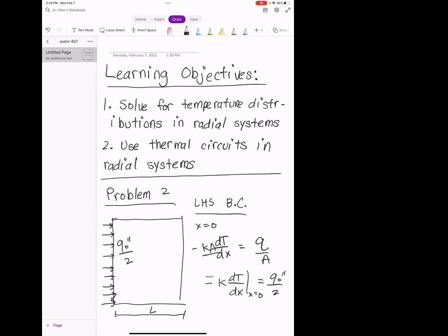The question was, why do we have this negative sign out here? That negative sign fixes our sign convention so that we have a positive heat flow going from high temperature to low temperature. If you evaluate this term, it is always going to be the temperature on the far end versus the temperature on the near end.